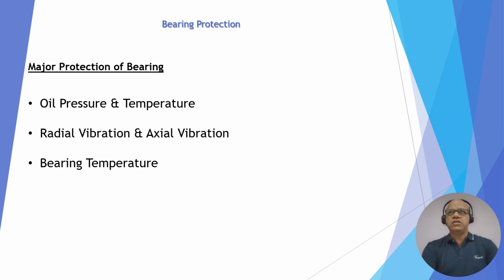So normally the rotor on the active side, let's say on one side, is touching, not touching because there is an oil film, but you can consider it is very close to the babbitt. Some manufacturers give some tolerance or some value for wear out of the babbitt, and it is sometimes 4 mils for alarm, 6 mils as a trip. Some manufacturers also give 5 mils as alarm, 10 mils as a trip.